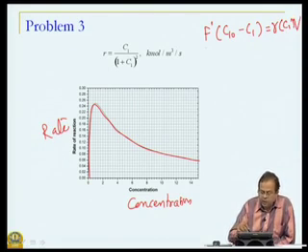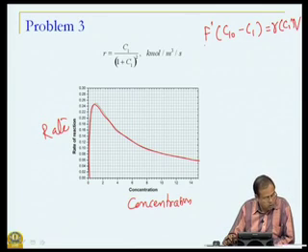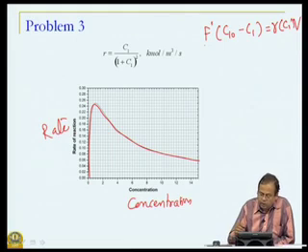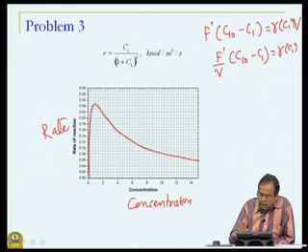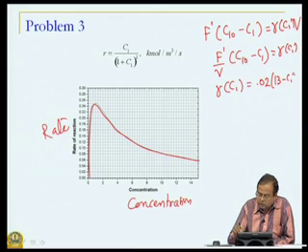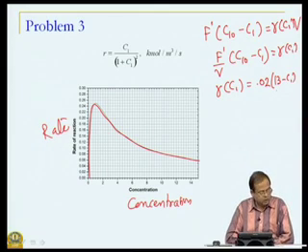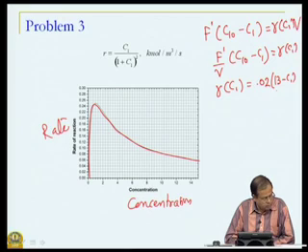We have been given F prime, we have been given C naught and all those quantities. So, we can actually write F prime by V into C10 minus C1 is equal to R of C1, and if you put all those values, R of C1 is 0.02 into 13 minus C1. That's just some number.